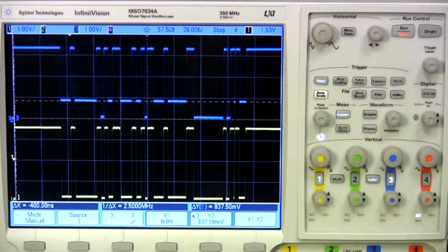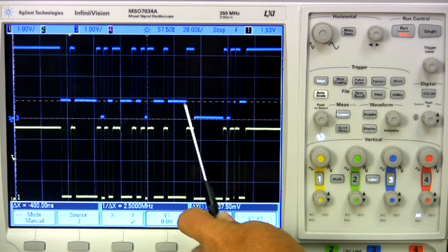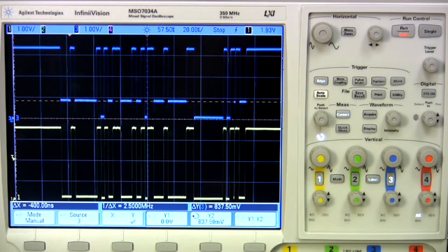Here are the SDA waveforms on each side of the isolator. The blue traces the A side and the yellow traces the B side. When the isolator is pulling down on the A side, it pulls to VOL. The Si8452 pulls down on the SDA during the acknowledge portion of the I2C waveform. When the Si8452 is pulling down on the A side, it pulls to a voltage slightly higher than ground. The isolator VIL is centered between the isolator VOL and the Si8452 VOL. This allows the anti-latch circuitry to work.